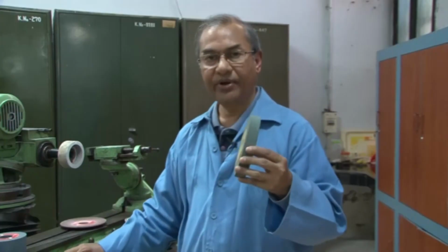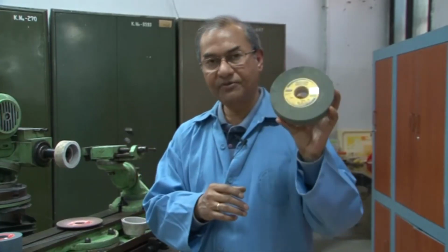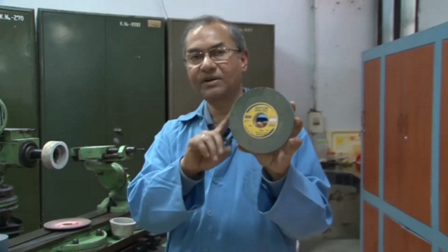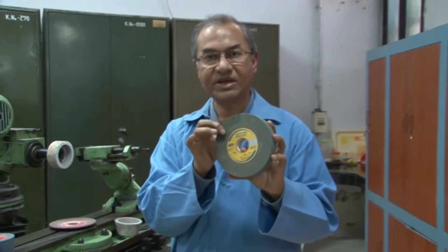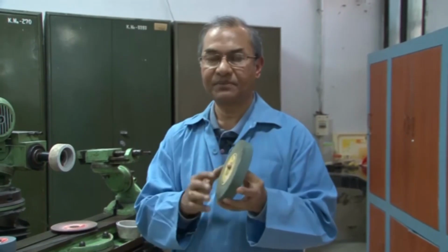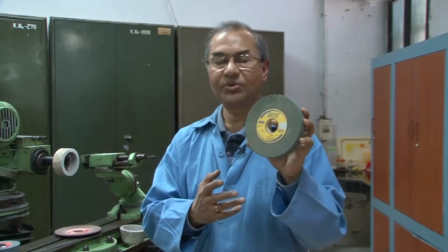Now, regarding the grinding wheel, I will just remind you that there are 5 parameters which define the working of the grinding wheel. The first parameter is the type of the abrasive material. Basically there are 3 types of abrasive materials which are used. I am repeating once again, these details you can see in the lecture material. It can be Al2O3, aluminum oxide, silicon carbide or diamond. Aluminum oxide, silicon carbide or diamond are used depending on what kind of workpiece material you are grinding.